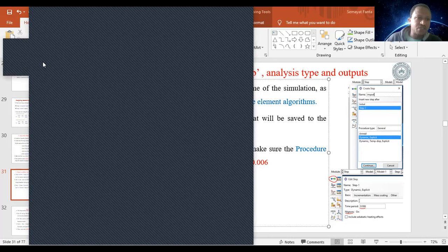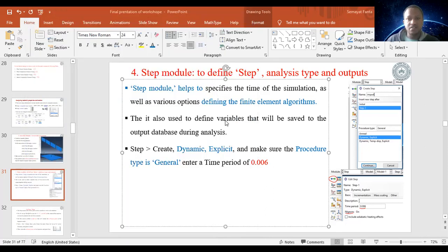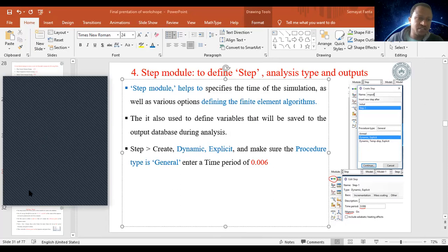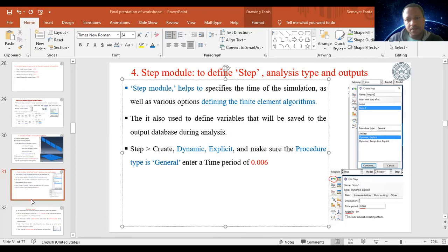And the type of contact should be tie constraint. So all the plies and the interfaces are in tie constraint. That is done. And let's make interaction between the impactor and the top ply. So for that, let me separately generate surface to surface contact. Let this surface be the first surface, the brown color.